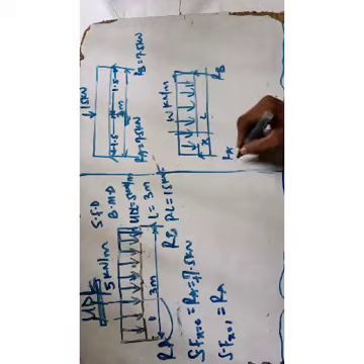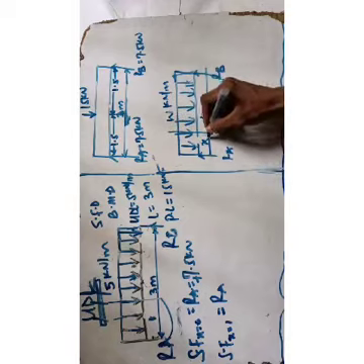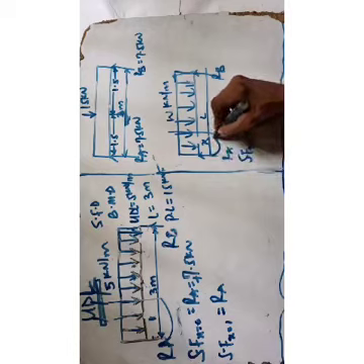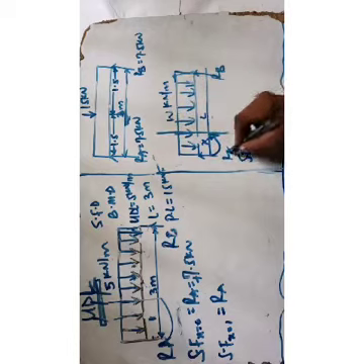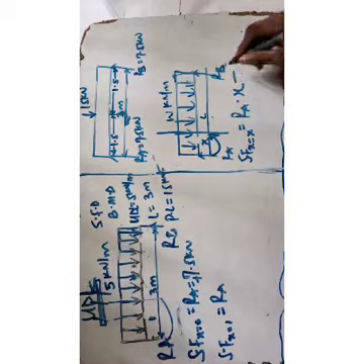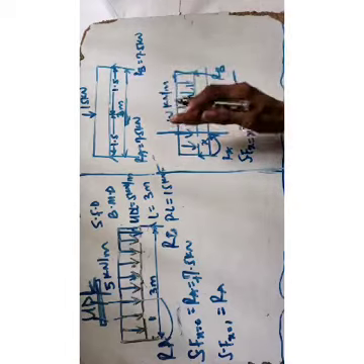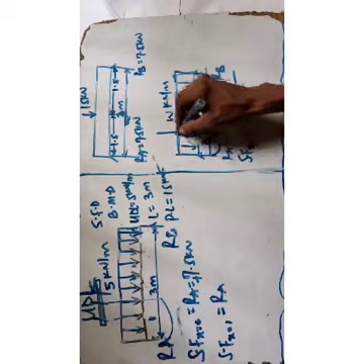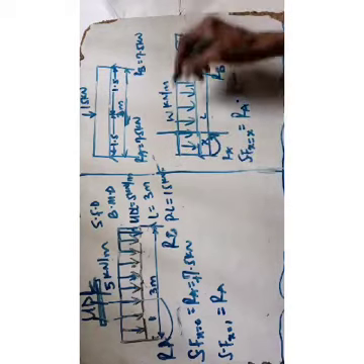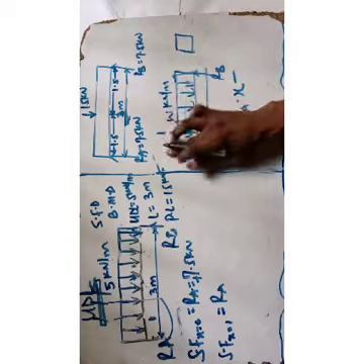If you want to take the shear force at point x, it will now be equal to this RA, when we multiply by the length, it stops here. That will be RA times x minus, here you're going to have this particular portion for this x length. You can say this is the weight, W kilonewton per meter.